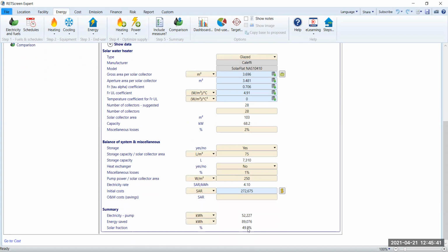You know, the solar fraction, the value of the capital F that we have been calculating today as a lengthy procedure. We have to go month by month and so on and get the summations. At the end, this is what we find, that it's about 49%. This is for a number of collectors of 28. What if I need to raise this to 75%? Maybe I need to change this from 28 to 50 collectors. Oh, we're close. That will make it maybe something like 54, or 53.